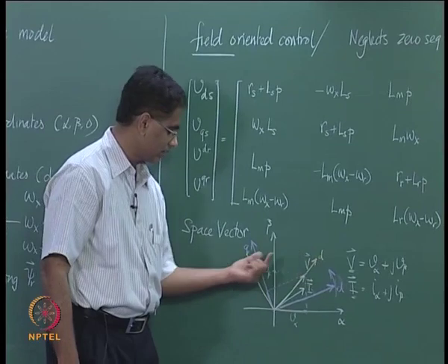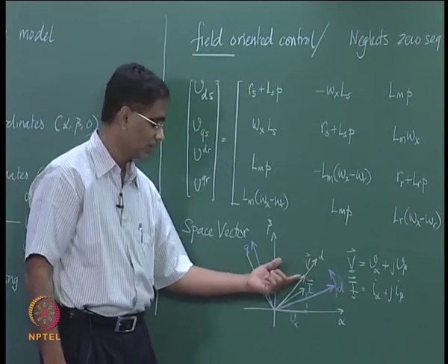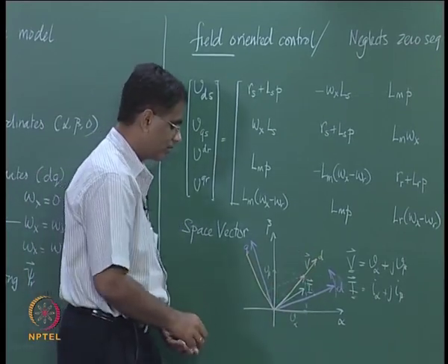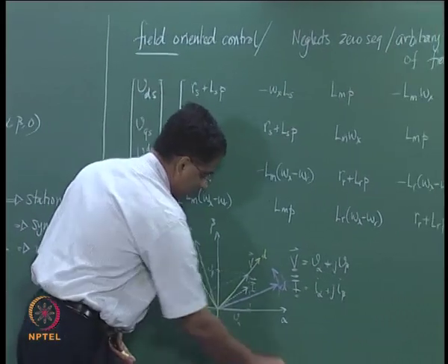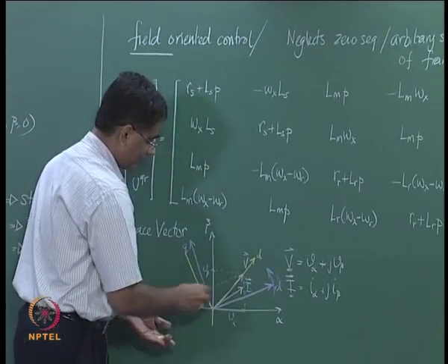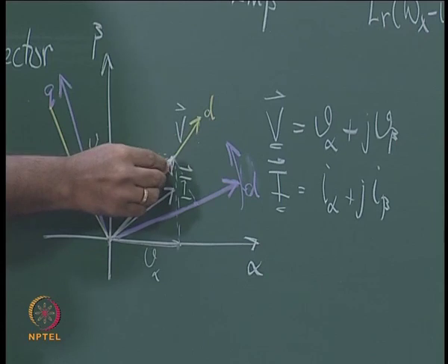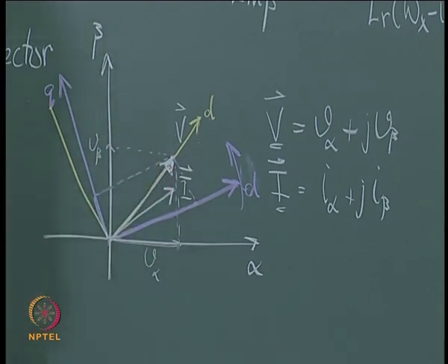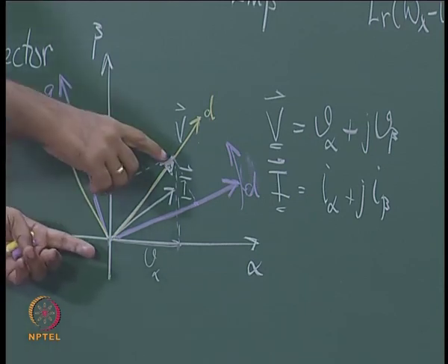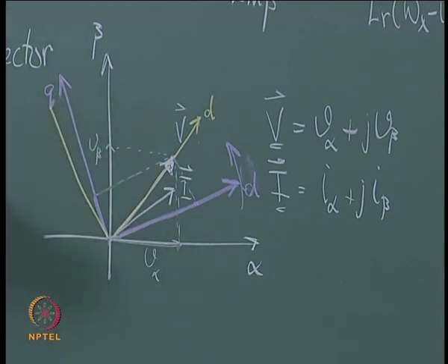So in this manner, depending on the axis that you choose, the individual two terms will change, but what is important to remember is that the space vector itself is not something that is depending on the axis, the length of the space vector and the location with respect to the stationary frame. So one can then reduce this description to the space vector notation.